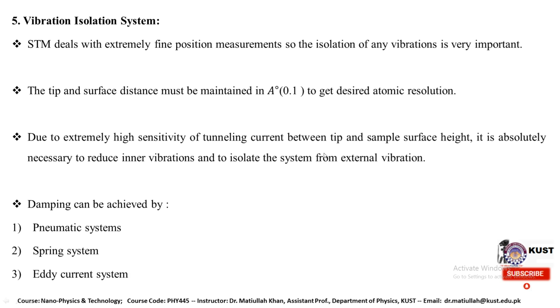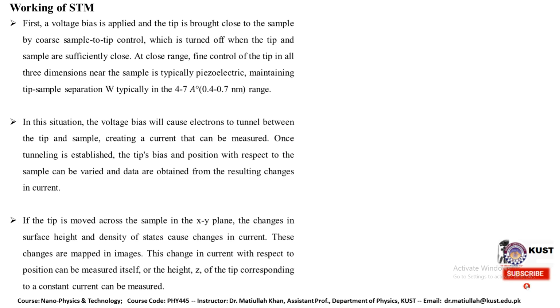Due to the extremely high sensitivity of tunneling current to the tip and sample surface height, it is absolutely necessary to reduce internal vibration and to isolate the system from external vibration. So the damping can be achieved by a pneumatic system, spring system, or eddy currents.